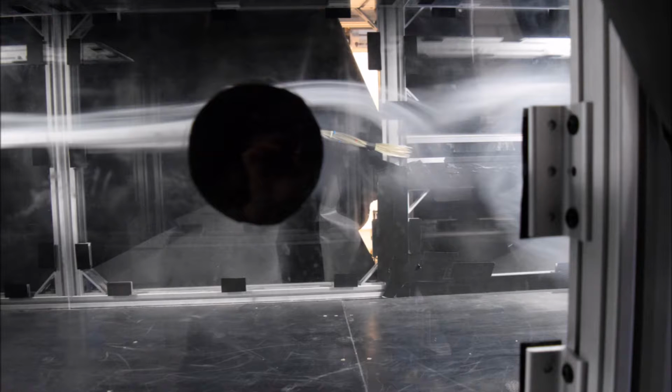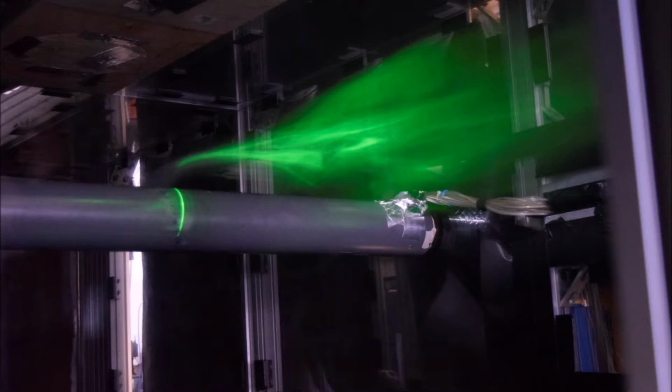After allowing the wind velocity to stabilize at 230 RPM and repositioning the smoke machine for the ideal streak lines, various pictures and videos were taken to record the visual effects the cylinder had on the airflow. Next, the wind tunnel was increased to 460 RPM, or approximately 20 meters per second, and the process was repeated, with several more pictures and videos taken to document the visual characteristics of the flow. After observing visually the flow at 460 RPM, the smoke machine was turned off, a clearing period of about 2 minutes was allowed, and then pressure measurements on the cylinder were taken using SCANavalve. 2 sets of pressure data were taken, the wind tunnel was slowed down to 230 RPM, allowed to stabilize, and then 2 more data sets were taken at this speed.